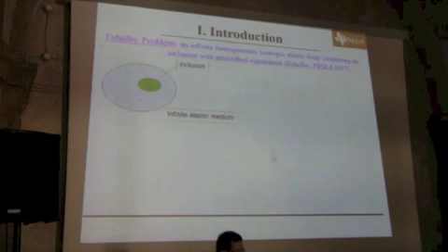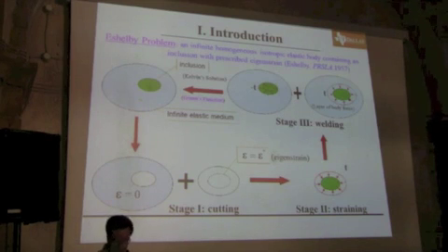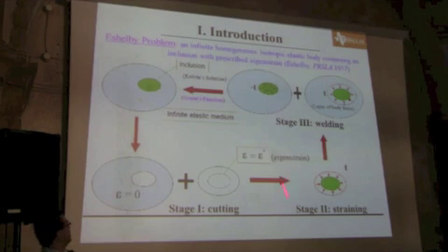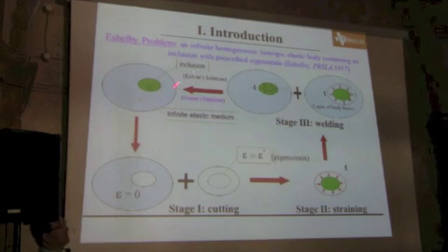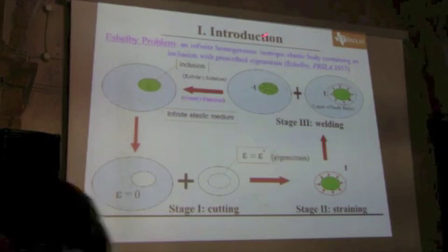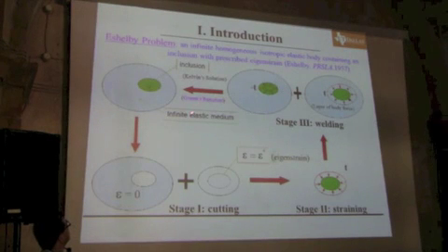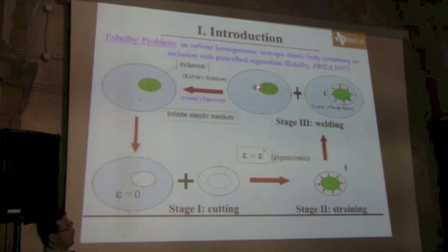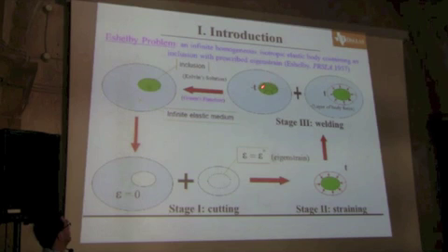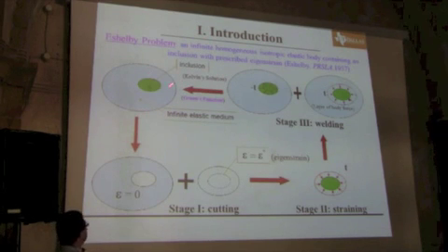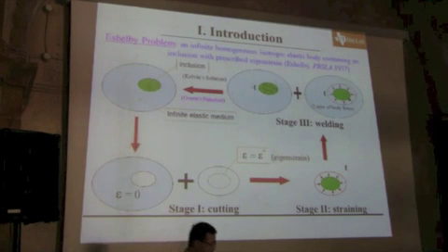On the next slide I review what Eshelby did in 1957. He was basically using a superposition method as an engineering approach. You cut the inclusion out, with nothing applied, no body force and no contact force, and then you cut and assemble. Because nothing is applied, you have to cancel that traction. The second step is nothing but a Kelvin solution in classical elasticity. Just do superposition, which in this case is an integral over the domain surface. When you have the distributed traction vector acting as a body force, you recover the original problem, which is a homogeneous, isotropic, infinitely large domain containing an inclusion.